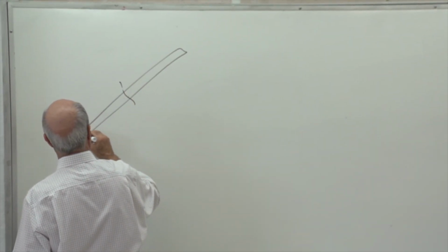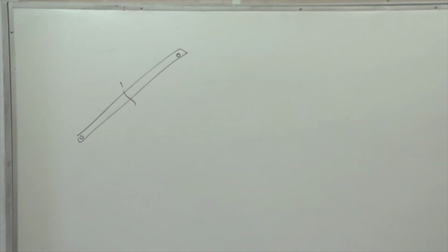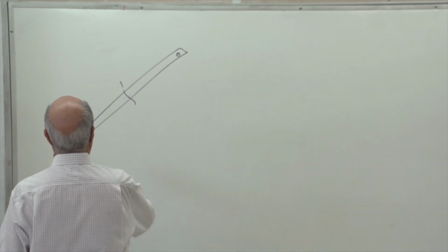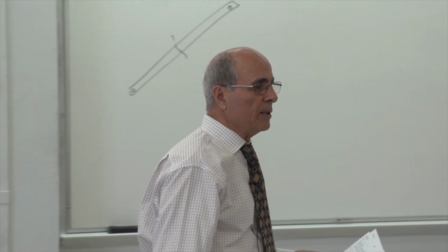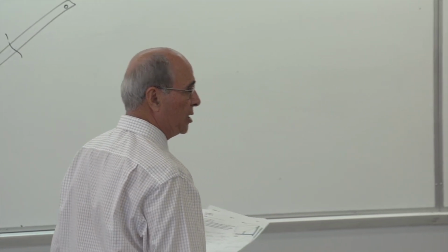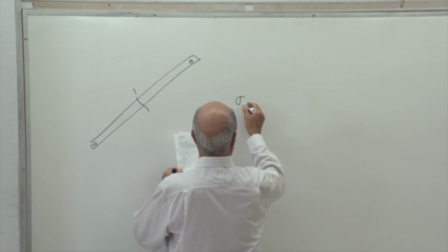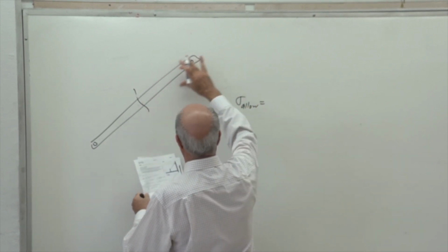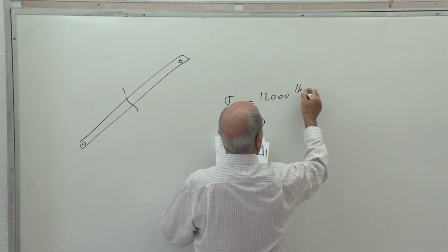This rod is under force and the pin is under shear. As simple as that. How else can you go wrong? So if you end up with the wrong FBD, at least this part of it should have been correct. I gave you credit. But you have to follow the rule. The rule is, first of all, look at the end. The end is being reinforced, so you do not need to subtract the whole area, yes or no? And of course, it is under tension. Therefore, you write sigma. Sigma allowable was given for this rod or that cable, equal to 12,000 psi, or pounds per square inch.